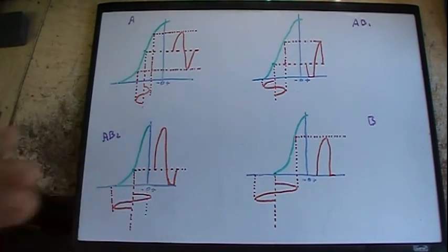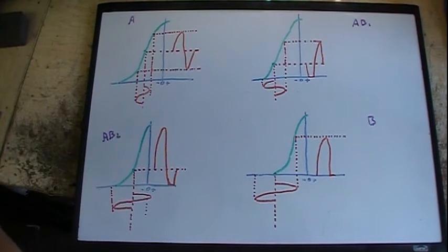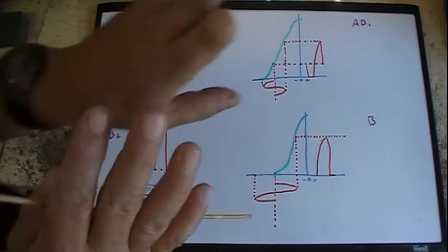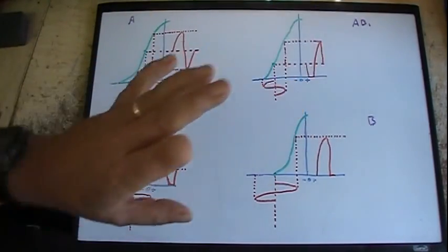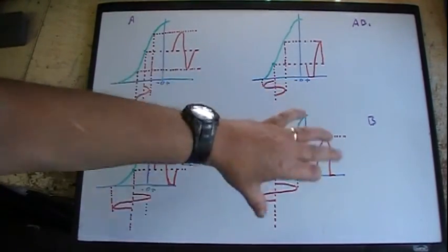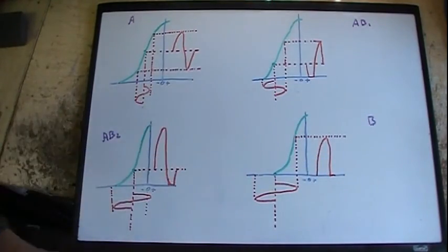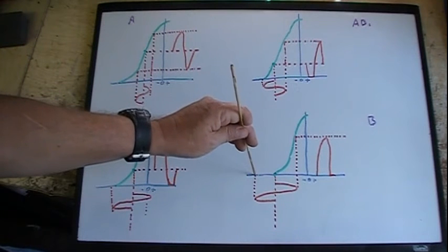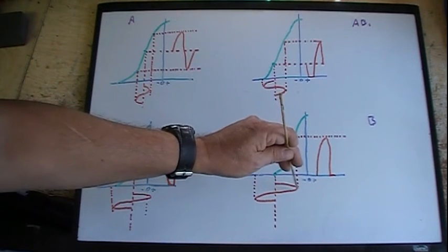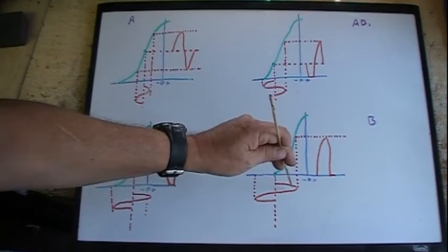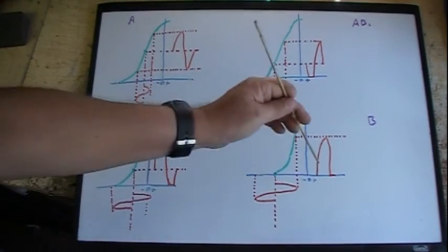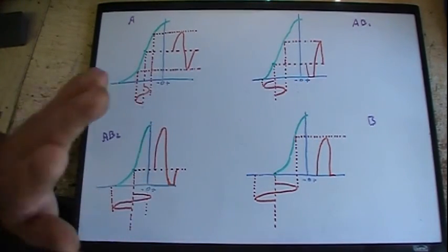Like I explained before, an oscillator, think of it like you've got a parent pushing a kid on a swing. Once they get them to where they want them at, they don't want to go any higher, then all they got to do is just give it a little shove every once in a while. Well, that's what happens with the tube and the oscillator. It just gives a little shove once in a while, and the way you design that is just bias the thing extremely negative, so that only the highest peak going positive will be a little bit of output from the tube, which gives that little push.